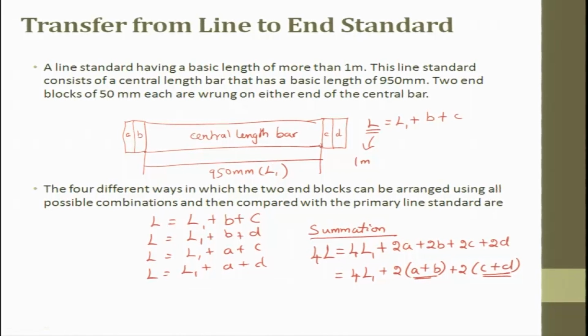Here this is the length bar, and we are attaching these two with 2 slip gauges. We ring it. Ringing is basically when we attach 2 slip blocks, there can be a possibility of air, thin film or non-contact. So we make sure these 2 surfaces are tightly in contact, we squeeze out whatever thin film is there, and then we ring it, and these 2 are attached properly.